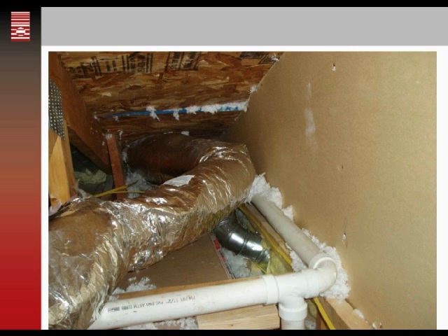This is another vent like that one we saw in the other photo, only this is going down the front of the house. This is the 2 bathrooms from the upper floor that are being vented out through, again, down that vaulted area. So this is a flex duct that's running all the way down and venting out through the soffit. What we ended up doing to get some low venting to this attic space without having to tear everything apart was we revented these bath fans up through the roof and used these ducts going to the soffit as our air intakes.